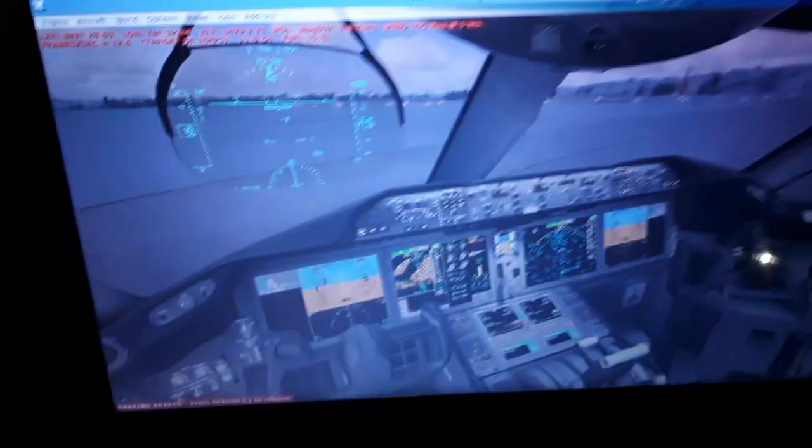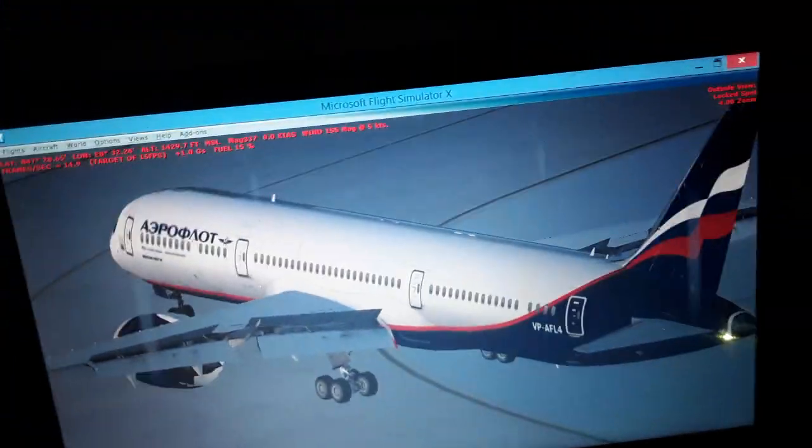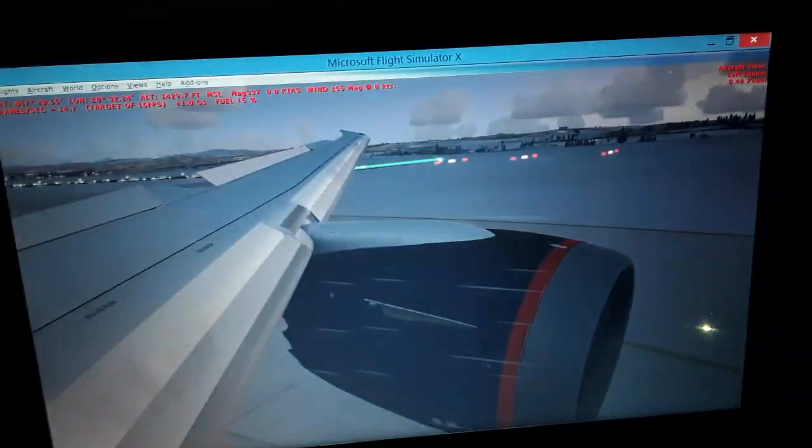For the mean aerodynamic chord position, where the maximum aerodynamic lift occurs and where the stall begins in the wings. We're going to be having the center of gravity and the horizontal stabilizer trim for takeoff at 25 degrees over here. So we're going to be having the flaps for takeoff. I'm going to set 15 degrees of flaps, and the flight management computer is going to calculate.